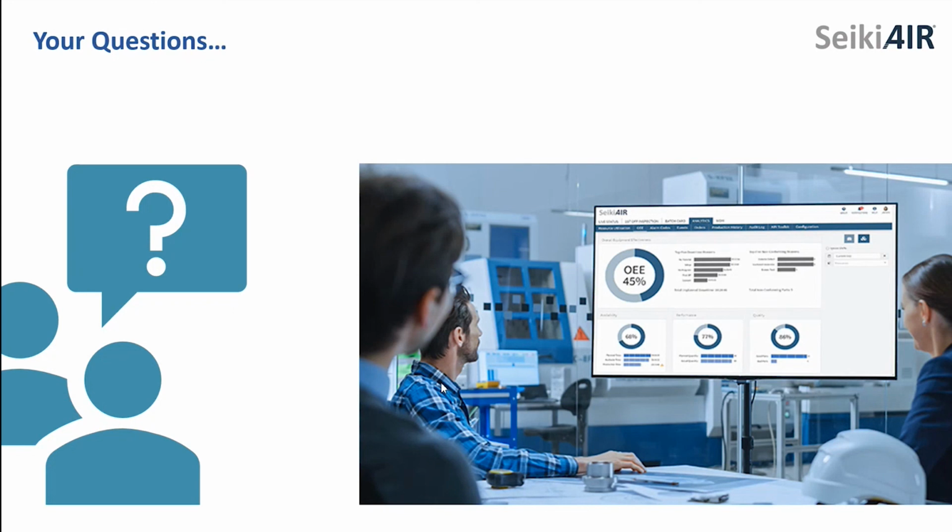So one of the reports Jamie mentioned, the plan versus actual report, you would tend to run that and review it over a period of time, not just because you've had one machine and one job that was performing particularly well with a really good operator. You might look at what your actual setup time and cycle time is on a particular product or group of products, maybe over a 3-month period, and then make an informed decision whether you need to modify that in your ERP. And as Jamie says, if you've got our scheduler or any other scheduler in between, the scheduling system can only be as accurate as the accuracy in your standard times.